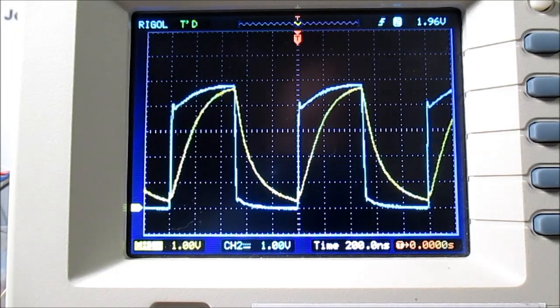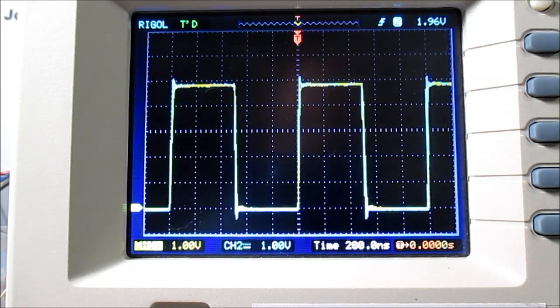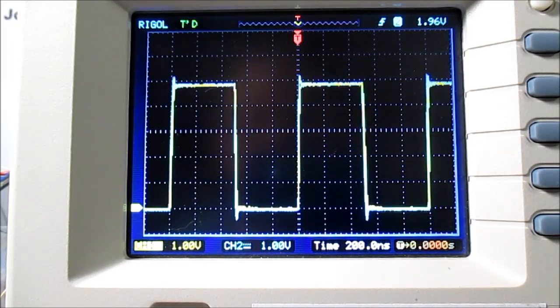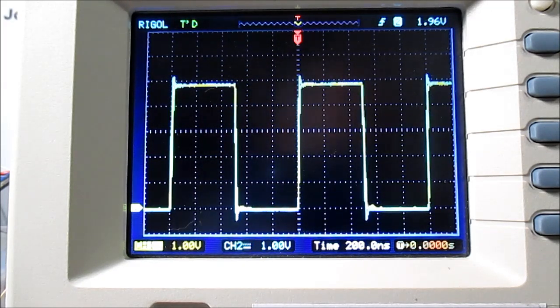And I think it has a little bit more capacitance. I mean, it's a beefier 10 amp diode. So there is more capacitance in the Schottky diodes that I'm seeing here. That can be detrimental depending on your design, especially in very high frequency switching. Okay, that was interesting. Let's move on to the forward voltage drop test.